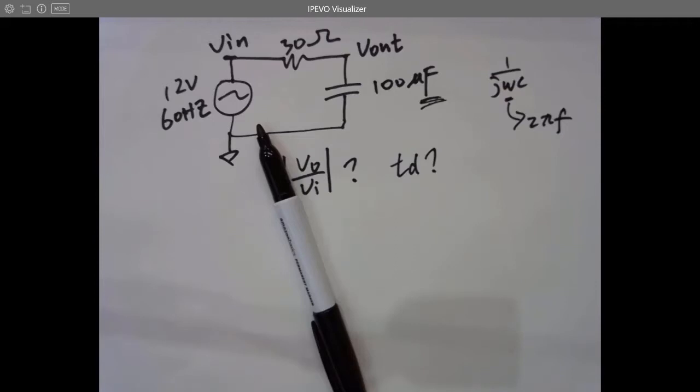So when the frequency is getting lower and lower, finally going to 0, DC is going to be blocked by the capacitor, cannot penetrate at all, right? That's why when it's getting higher and higher frequency, it's easier to pass the capacitor. So with the high frequency component for a signal, the capacitor is working as a short circuit. Little tiny resistance. It's going to short the circuit wire.